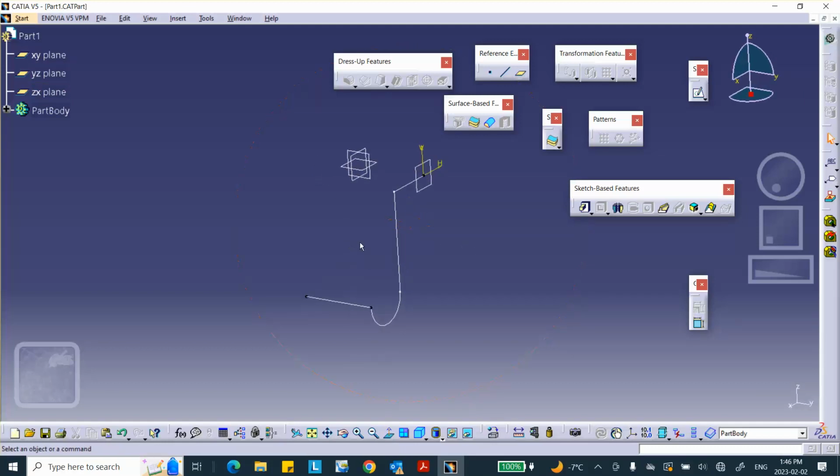Okay, very good. Now, I'm going to join these two. And I mention this because if I don't join the sketch and the line, when I measure at this corner point, I have duplicate nodes, one from the left, which is the line, one from the right, which is the sketch.